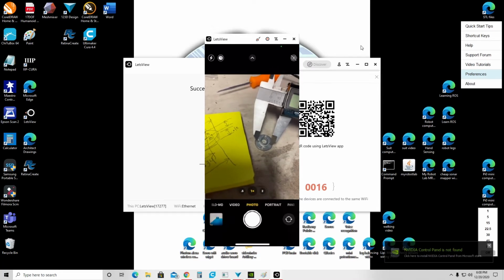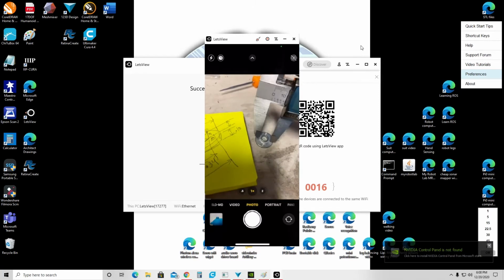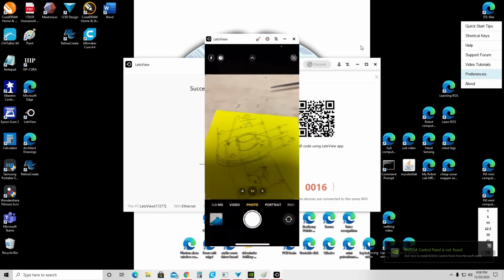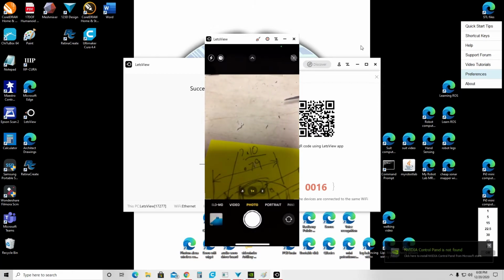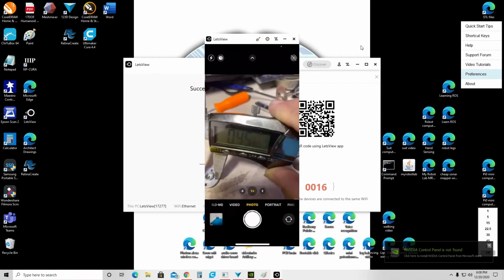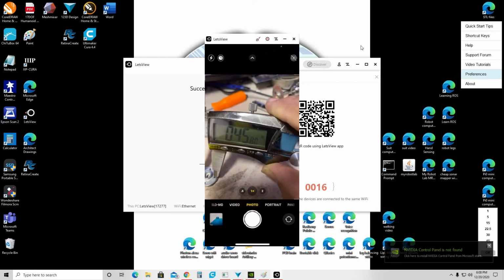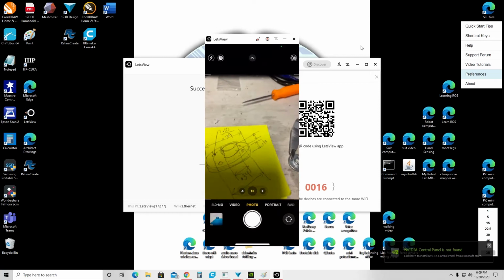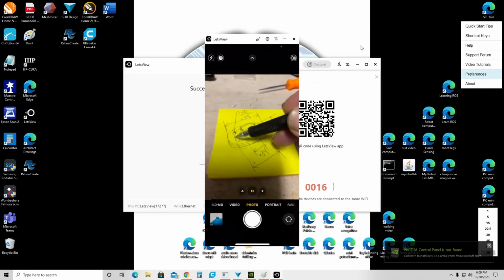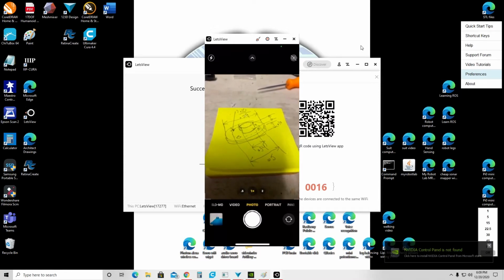So all we have to do is measure the inside diameters and add 0.10, because we already know the part was 0.10. My number says 0.458, which is 0.46. Adding 0.10 is 0.56. So I go back here, and I know that those holes are 0.56.